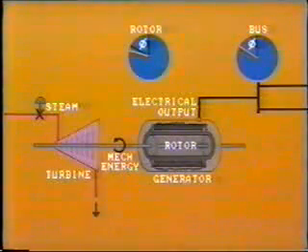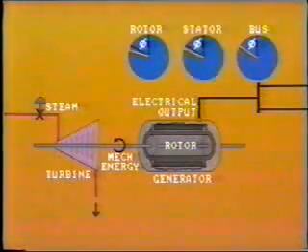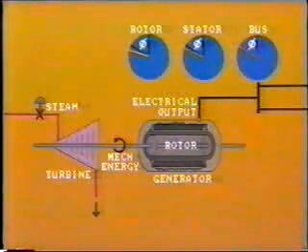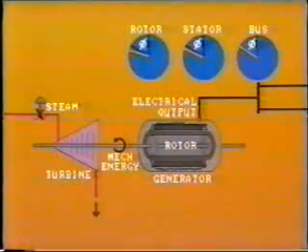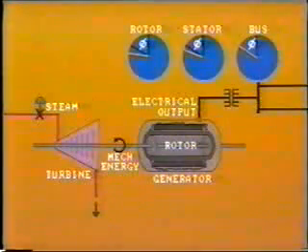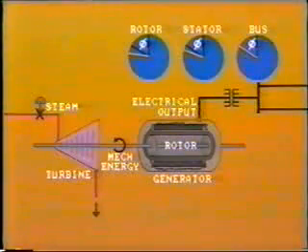As the rotor accelerates and moves ahead, so does the corresponding voltage, which is generated in the stator windings. There is actually a small angular displacement between this voltage and that of the bus due to the reactance of the generator windings themselves. Moreover, a transformer is often connected between the two, so adding more reactance. However, this is usually small in comparison with the reactance of the transmission line.